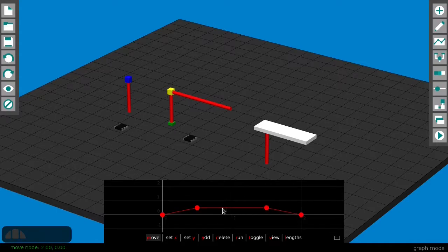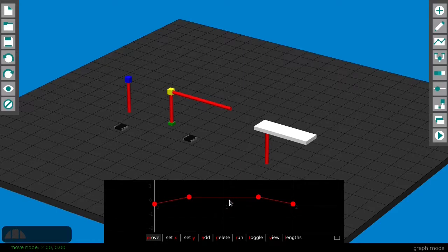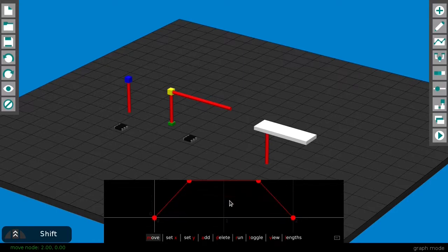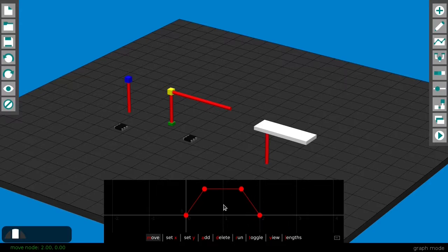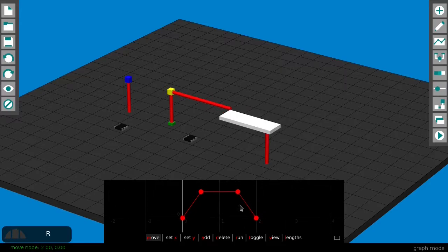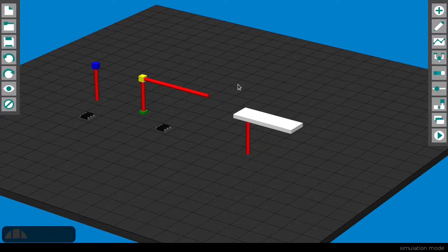This graph is too thin, it's hard to see. Change the aspect ratio by zooming with the shift pressed, then zooming back. Now you can see this track goes from value 0 to 0.5. Stays there for a second, then goes from 0.5 back to 0. That's all there is to moving things in MockMechanics. The only missing thing is the toggle button, which I'll explain later when we need it.